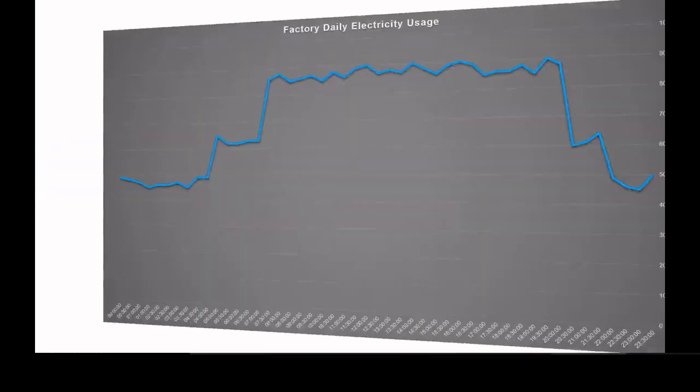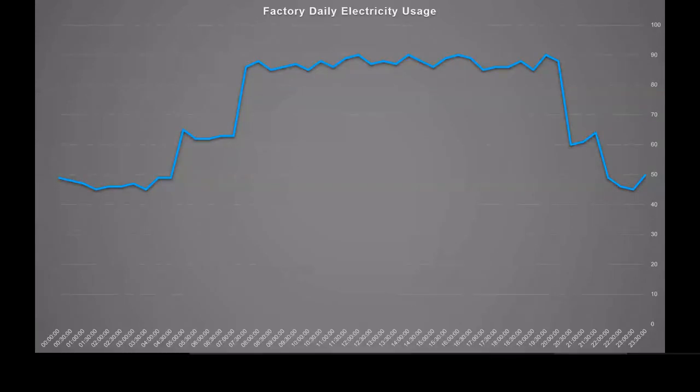So before we even started, we looked at this general profile. What can we learn from this profile? Well, straight away, the base load, or the bottom of this top hat, it looks like a top hat. You may have come across that top hat reference. The bottom of the top hat is actually over half the usage of the total profile. You're using at maximum maybe 90 kilowatt hours per half hour, whereas the bottom of the top hat is about 50. So on average, that's a really high baseline. That's the first thing that sticks out that we need to review.